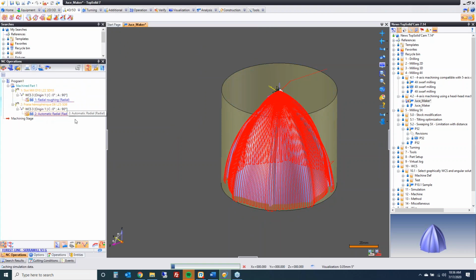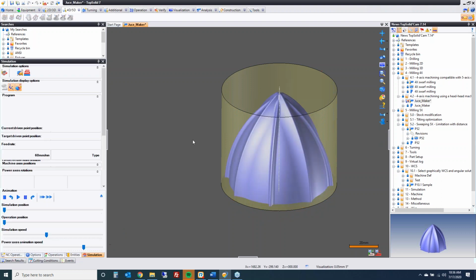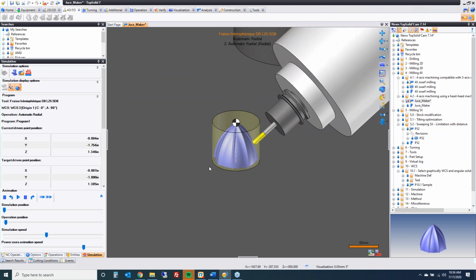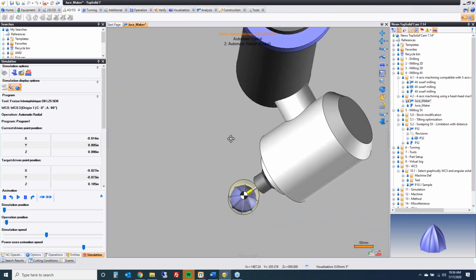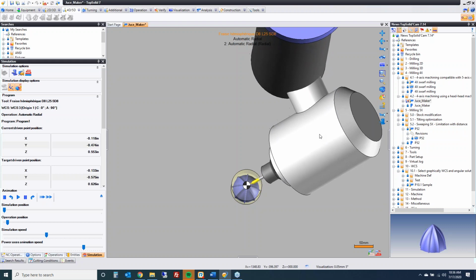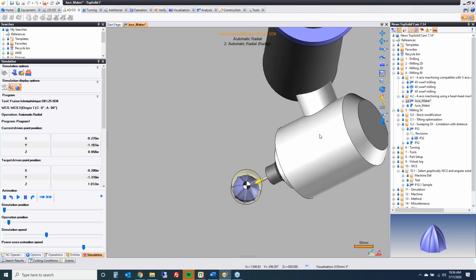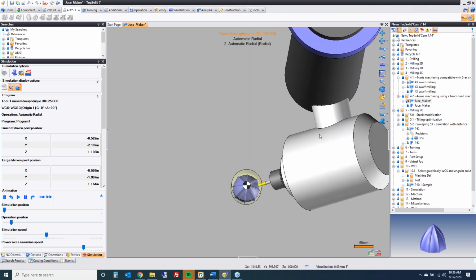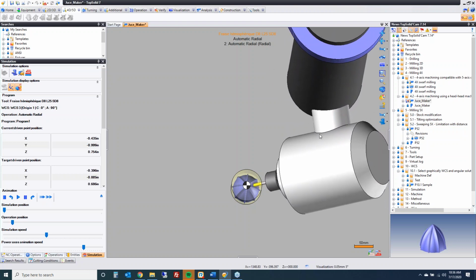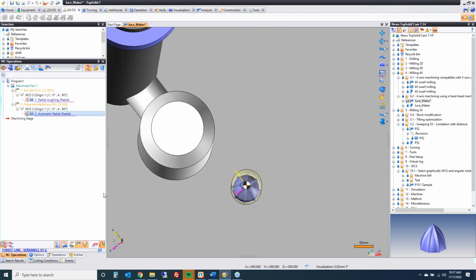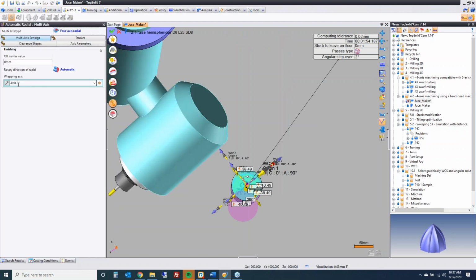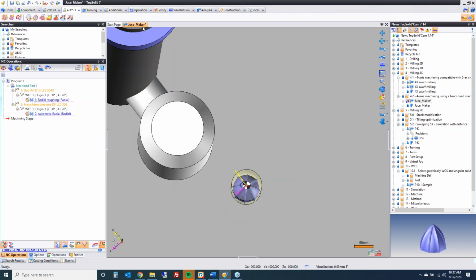If we look at the radial finishing, same concept. So here I'm using the head to just go up and down and index around the part. If we look at this kind of straight on, you'll see it index over every 2 degrees. So it's just a way to finish parts in 4-axis radial, however you want to look at it. Again, same feature because it's a cousin to this command. The only thing you need to worry about on a head machine is you have to define that wrapping axis. That's it. All right, cool.